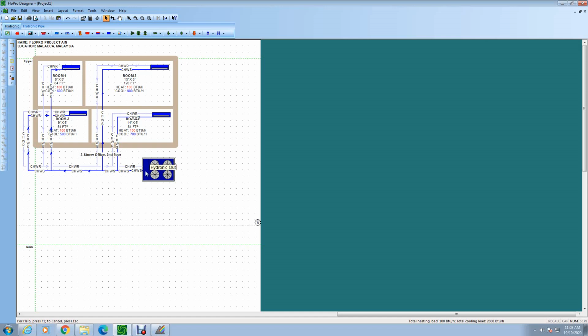Okay, you can click the cycle annotation view icon to see the exact total load carried from the buildings. Please ensure that you have connected all the piping, supply and return, so that the total load calculated is correct. Okay, you can play around with this cycle annotation view.